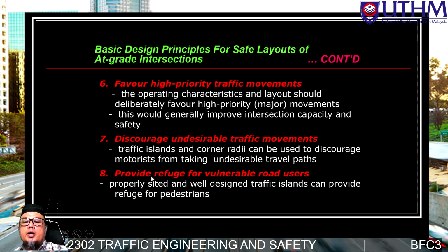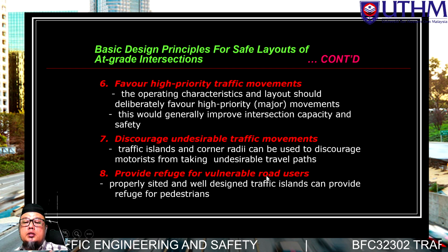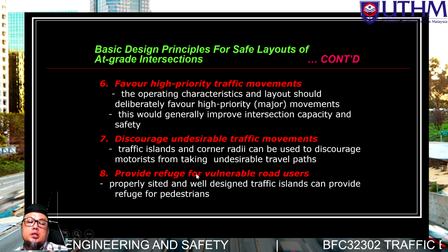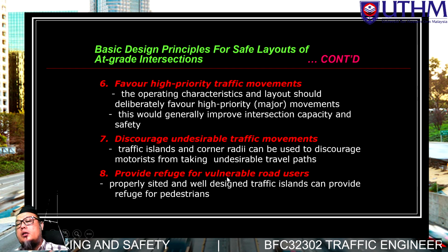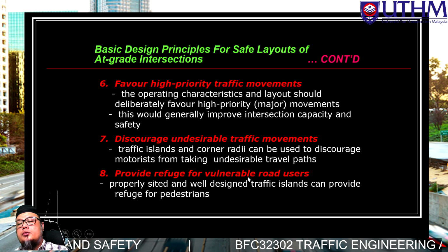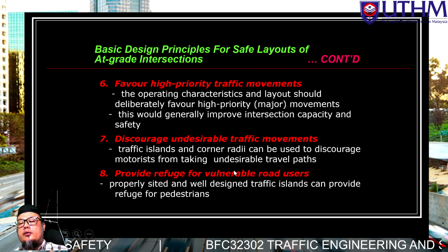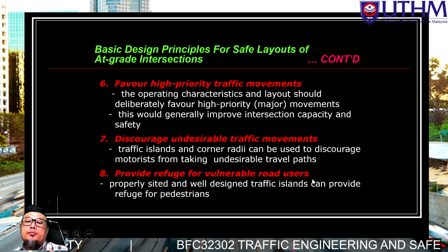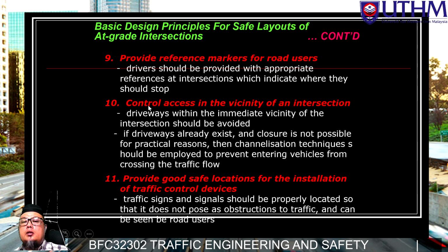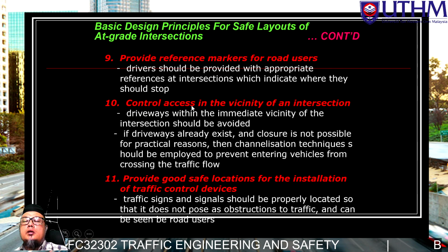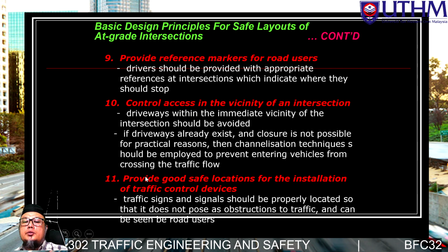Okay, eight, provide refuge for vulnerable road users. This is typically for pedestrians or cyclists that share that particular area to cross or to have their own direction of movement. Okay, number nine, provide reference markers for road users and control access in the vicinity of an intersection.